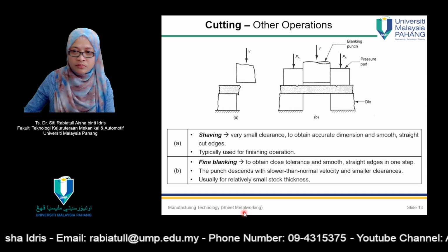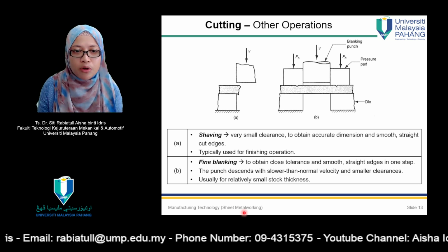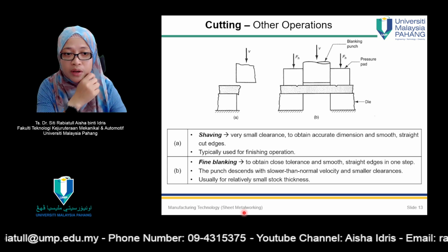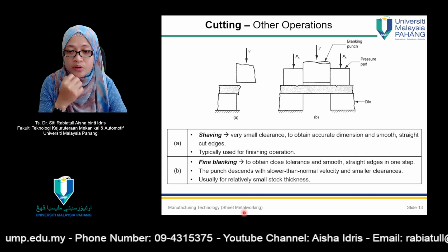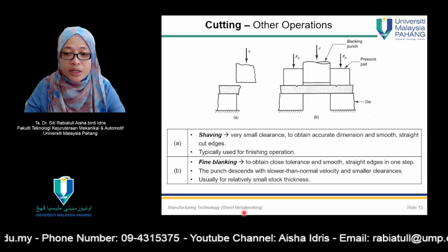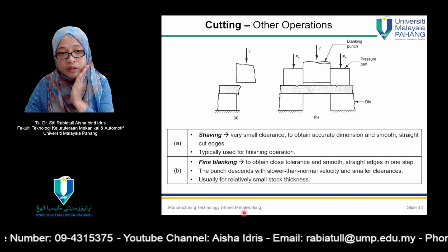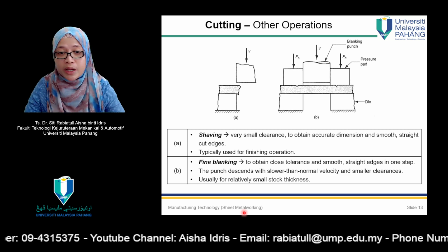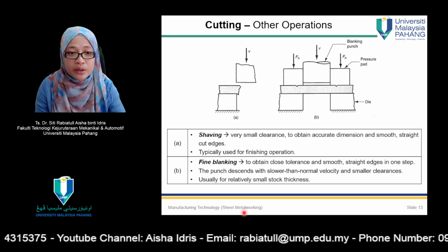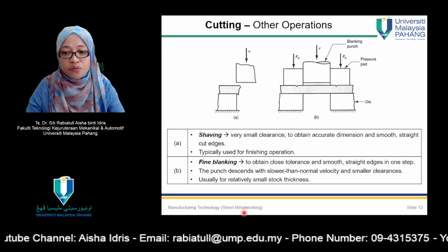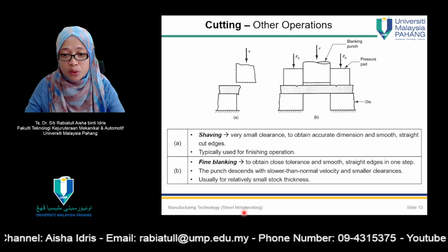Okay, there are other cutting operations included here, like shaving. Shaving is like you shaving your beard and so on. So it is actually removing a very small clearance just to obtain accurate dimension and smooth straight cut edges. Typically, this one is used for finishing operation only.